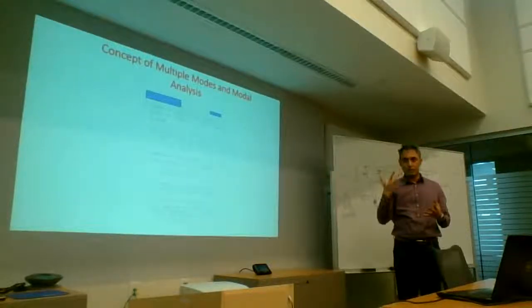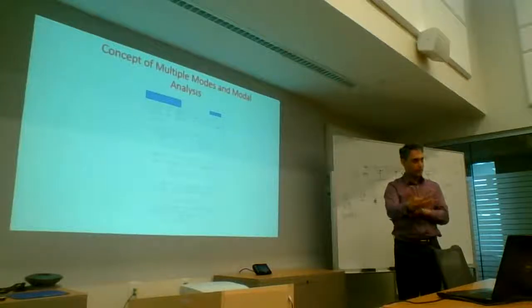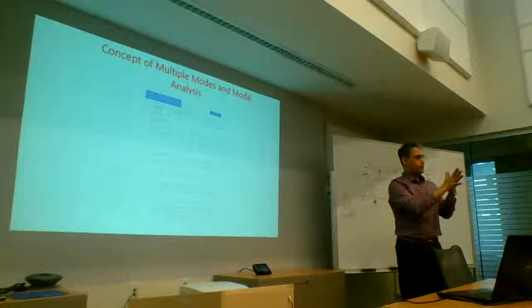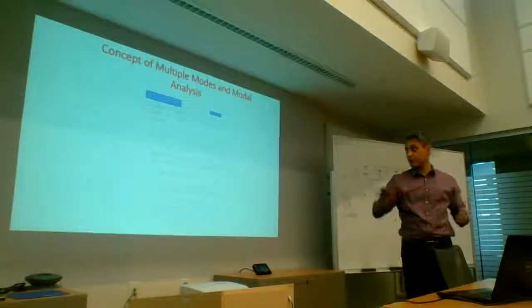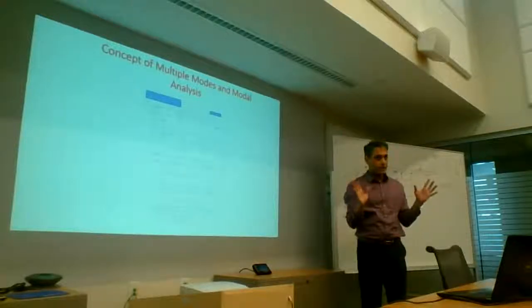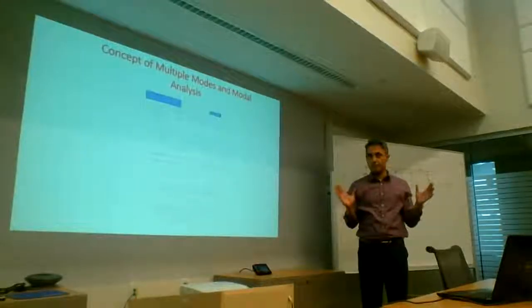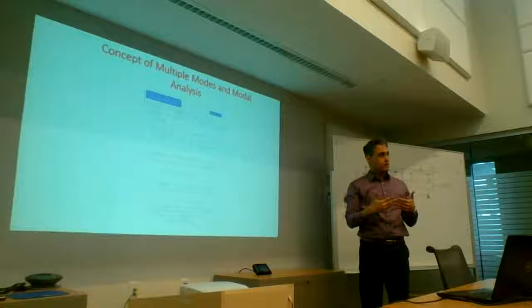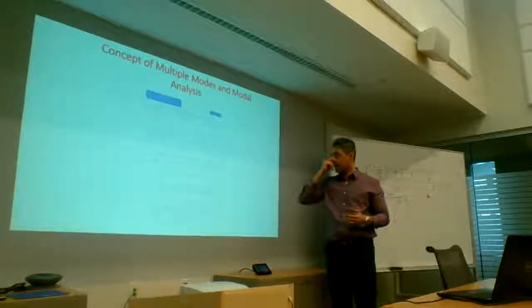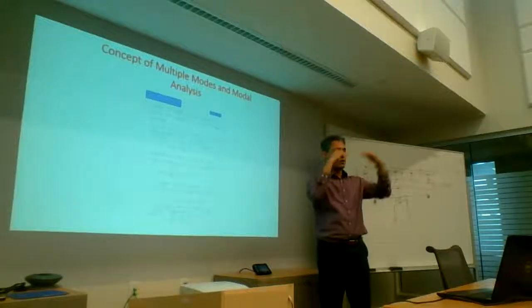If you're running a time history analysis, you can do this by not integrating the equation of motion. You can go through this modal route as long as it's linear, because modal is linear. You can use linear superposition because everything is basically elastic. You can do that, and then you're only solving in time history.